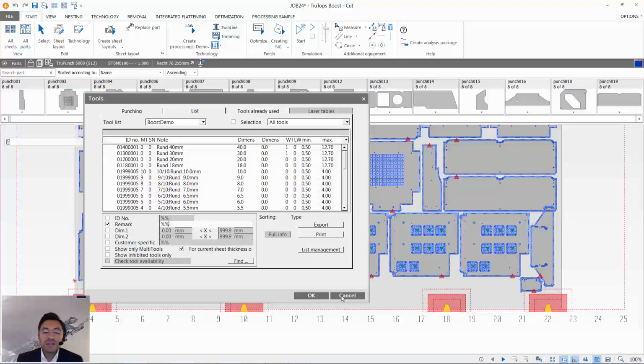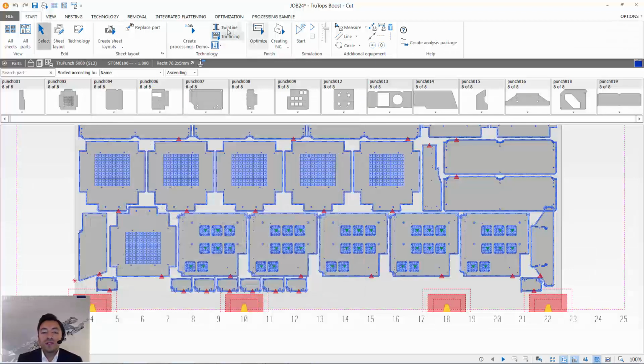And the best thing is, once you pre-configure everything, so from the parameters of your nesting, the processing configuration and the optimization parameters, there is a button which saves your parameters back into the automatic calculation.